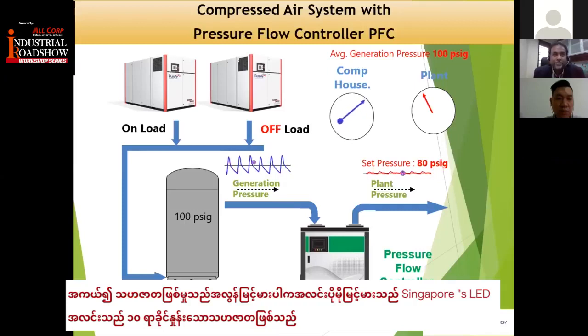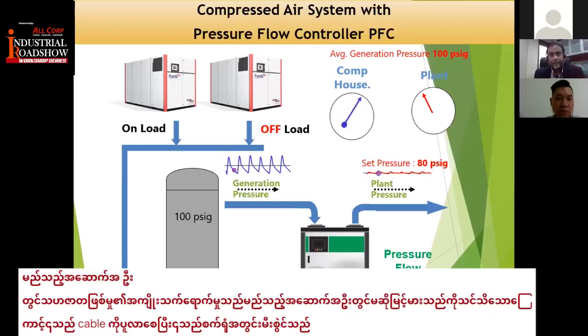So that's why you can ask for a reference point. Have you installed in any buildings in Singapore? If yes, then you know this supplier is the right supplier you are selecting, right? So you know what the effect will be if the harmonics level is high in any building. It will make the main incoming neutral cables become hot, and this will cause heat problems, and it can also cause fire in the plant, right?